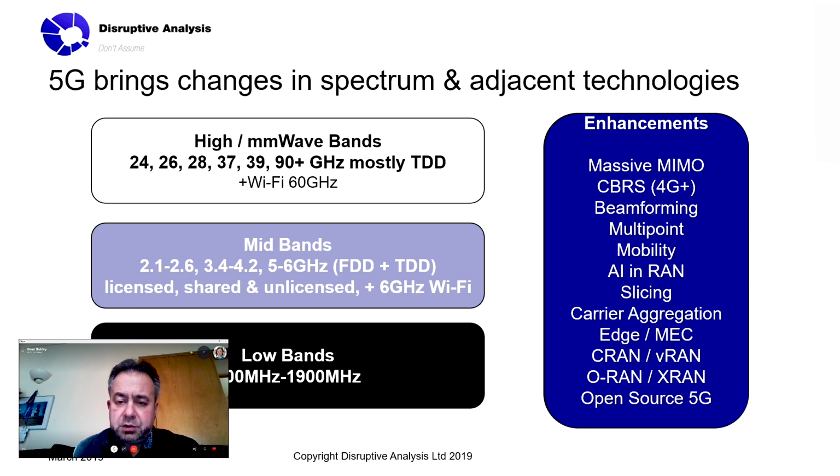The other thing I'll draw attention to now, towards the bottom of that panel, is the CRAN and ORAN, and that's Cloud RAN and Open RAN. We're starting to see various models emerge for disaggregation of the radio, both at the macro level outdoors, but also that extension into the in-building, which is where you may well see more splits between the electronics of the radio and the actual antenna linked together via fiber. There are various standards emerging for that, but that will have an interesting set of effects depending on the type of building we're in. Next slide, please.